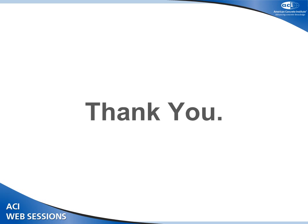Right. Well, on the first question, with the time factor and the slump loss over time, what we're recommending is that if you're going to do that adjustment, do it at the plant, not at the site, because you're going to have differences in time and differences in slump loss. Unless you want to go out and model that and have ways to account for that, it's really best to do the water adjustment at the plant. So the water slump correlation is established at the plant.